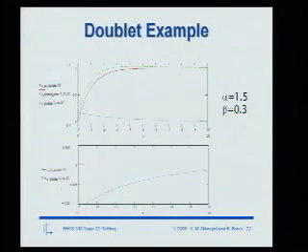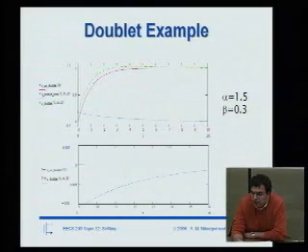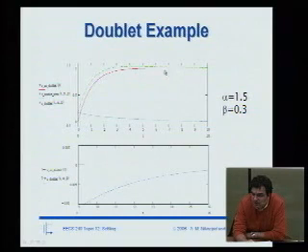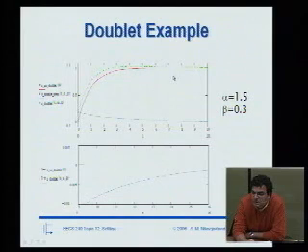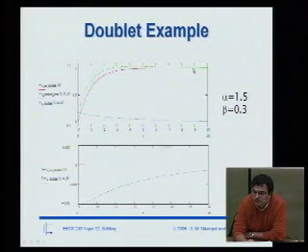So here's a plot showing you the effect of the pole zero doublet. This is the slow time constant that we're waiting for. This is the ideal step response in the red. The green is the step response with a doublet term, and then this is showing you how that doublet term is decaying to zero. So if I were really targeting high precision, I might want to stop here if the pole zero weren't there, but this extra little term is forcing me to wait another 5 or 6 time constants. Okay.